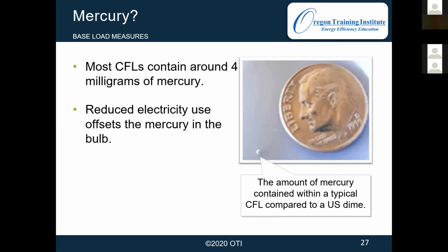And that's how fluorescent lighting works. It has a phosphorus coating on the bulb. You know, those long tube style ones, when you break those and it has the powder in there, that's the phosphorus. And when we add the mercury vapor and then the ballast at the end sends the right amount of electricity, and when that vaporized mercury is energized, it reacts with the phosphorus and creates the illumination.